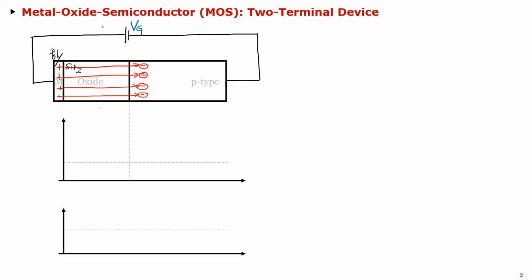Okay, so if I now plot the potential through it, I'll show you what's the key in what's called the inversion of the channel. Basically, this is a p-type material, but we want to invert this part of the channel, or any part, but I'll show you why this part is crucial because of our planar structure. We want to invert this part to an n-type.